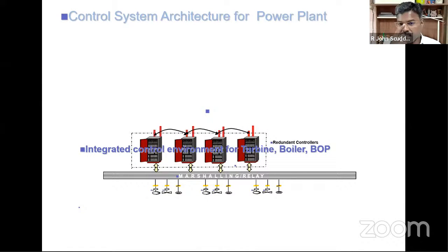As I told you, imagine his question was how the field signal comes in and how it comes to the human machine interface. Now this field signal, imagine we have a pressure transmitter. This pressure transmitter requires a power supply to power on. That power supply is given by the DCS module. If it requires 24 volt DC, it will go from the DCS module through the same wires which are connected